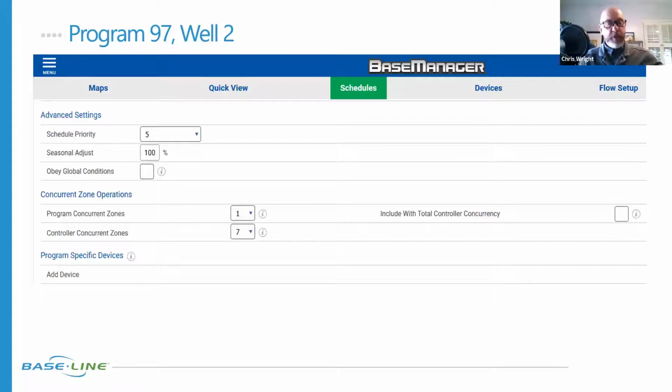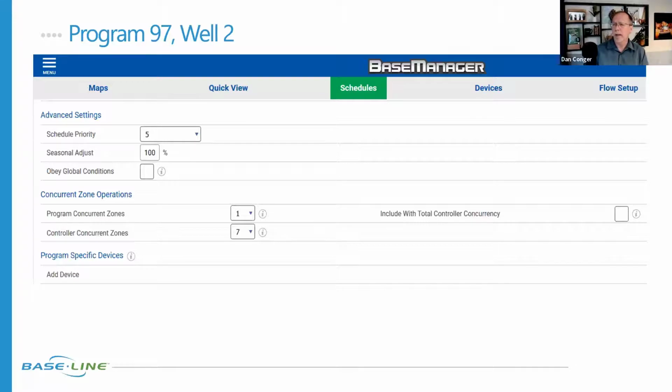What about schedule priority, Dan? This one, how does that factor in? It may or may not in this case, but how would it? Yeah, in this case, it actually doesn't factor in, because all of these are supplying water in. If they were using the city water supply as a makeup, they might use a priority there. Right now, I believe they're only using it as a manual, like emergency override. If we wanted to have the secondary water supply as a backup, we could probably use priority for that. But in this case, there is no application on that.